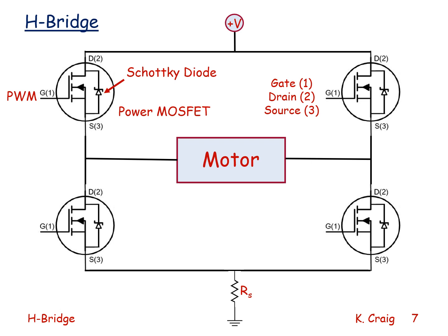Here we see the diagram of the H-bridge with the motor. Our 4 power MOSFET transistors, the pulse width modulated signal to the gate of each transistor, the Schottky diode for back EMF suppression, the flyback diode, the voltage source, the sensing resistor, and of course ground.